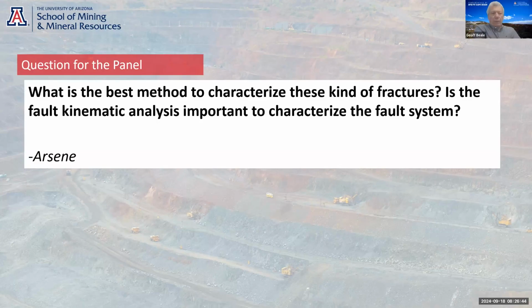So I think we've said that the best method is to drill a hole and test the hydraulics. Yes, the fault kinematics is useful, but fractures and faults, their hydraulic characteristics vary over short distances. So essentially, there's no substitute for drilling a hole and actually running hydraulic tests.